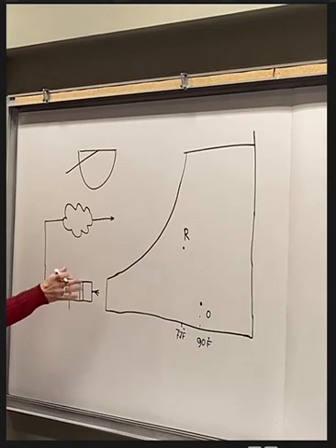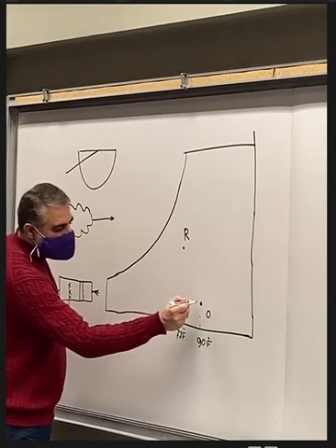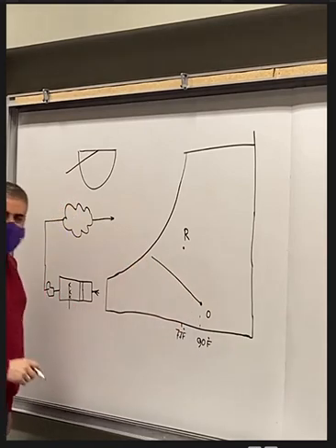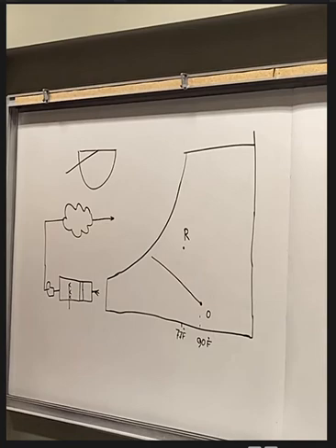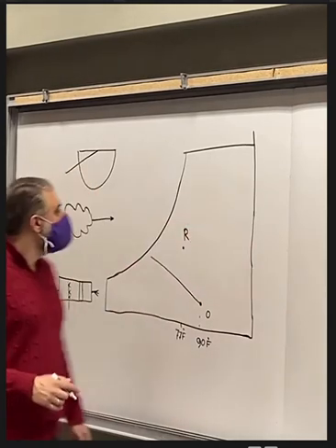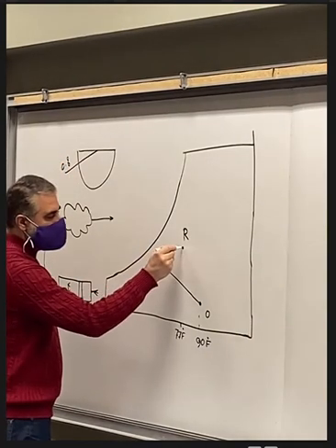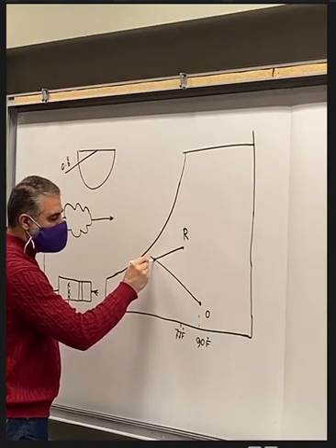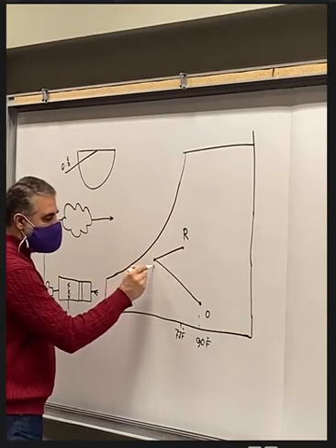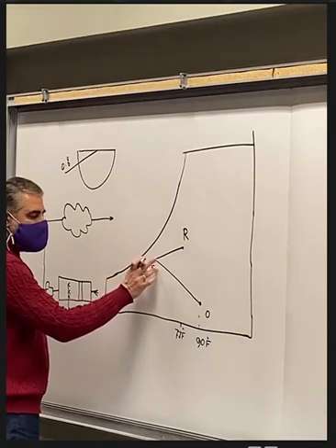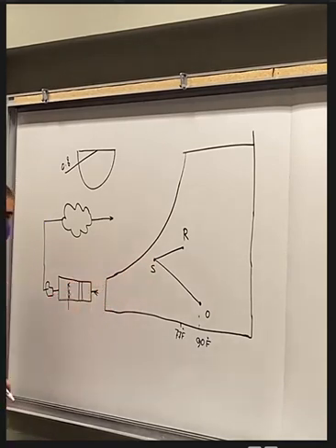So to simulate this on the psychrometric chart, if we allow the outside air to go through the adiabatic humidifier, it will follow a constant enthalpy line. Since we know SHF of the space, SHF equal to 0.8, then we can draw a parallel line, and that will be the supply air temperature and humidity to the space. Since we located point S on the chart, now we can size all the equipment.